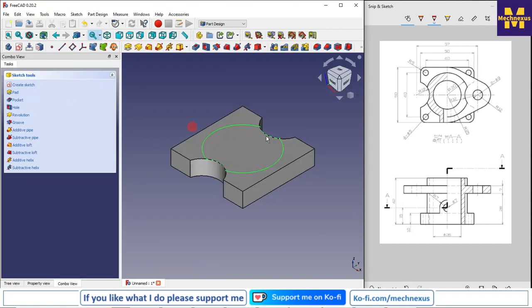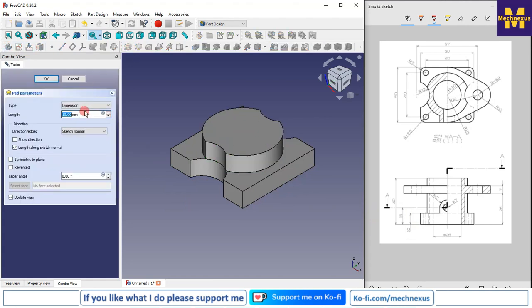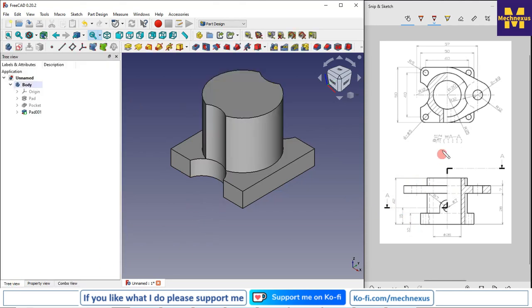Now I will close it, and the total height is 42 minus 10. So I will go with the pad and give here 42 minus 10, because the total height is 42 and the base plate thickness is 10. I will say OK. Now there is a hole and there is no material, so I could do the material removal operation later, or you can do it now. So let's do it. We will go one feature at a time.